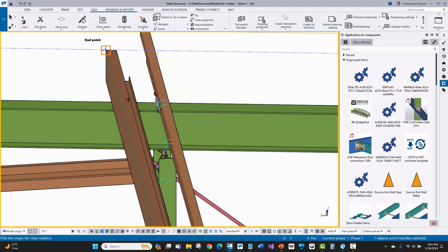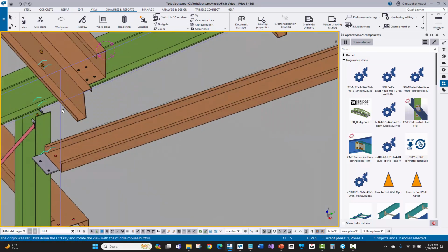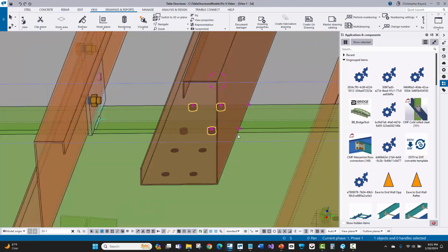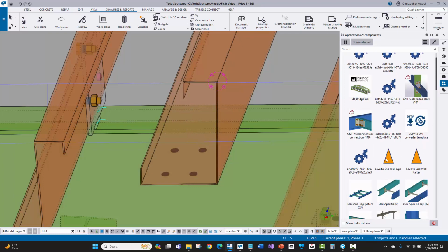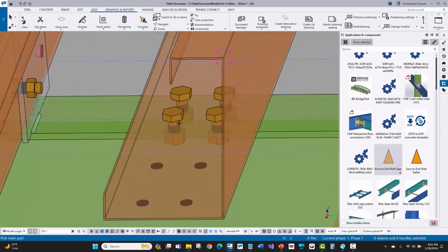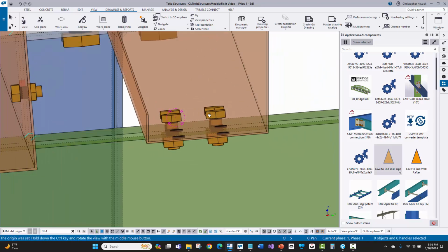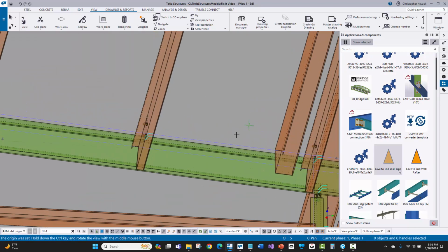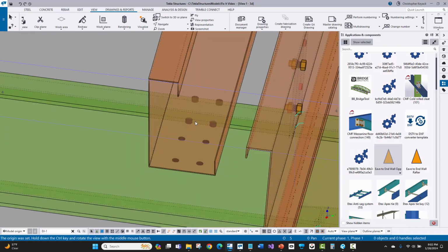It looks like that Eave is going on this end wall as well. So if I just come in here, what I'm going to do is Control 2, I see those holes. I'm going to get rid of those as well, and I'm going to use my component. Now, in this particular case, I bet you the opposite's going to work on this side, so I'll pick here, here, and looks like the orientation and the rotation of those bolts is spot on. Looks really good. Okay, so I'll go ahead and keep that, and then I'll go to the other side, and we will just fix this up really quickly. I'll grab these, delete those out, and then I'll use the original one that I made. I'll pick the Rafter, and then I will pick my Eave, and there we go.